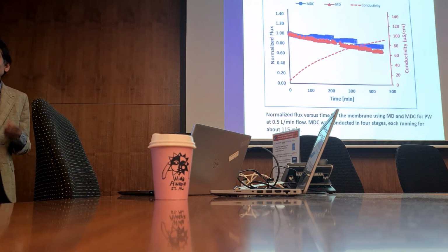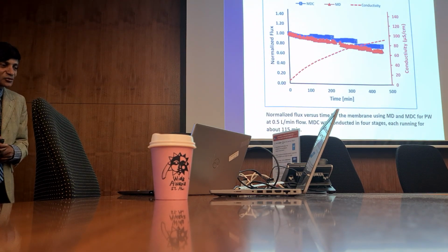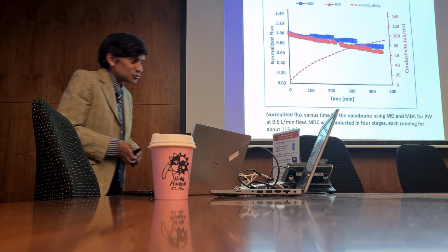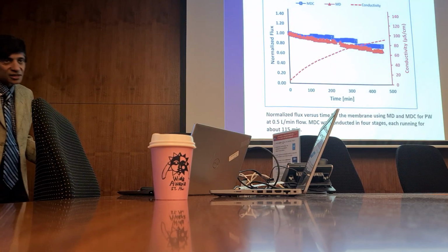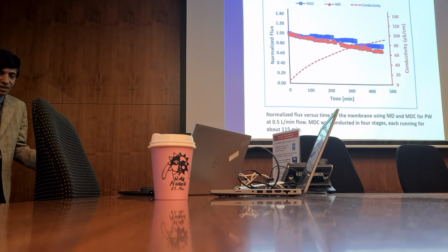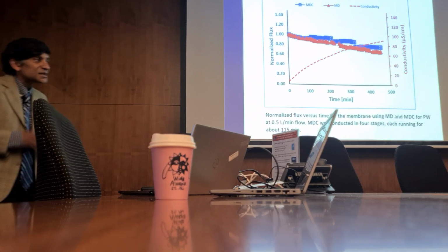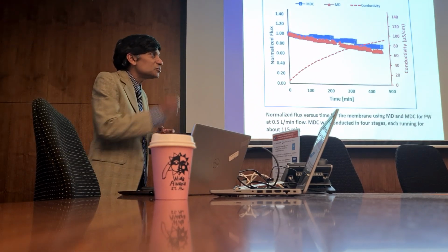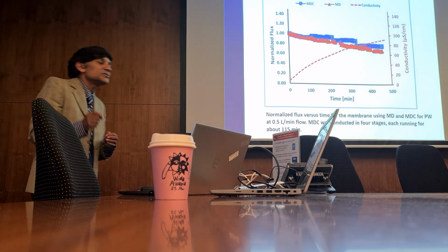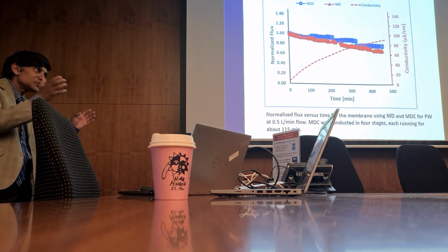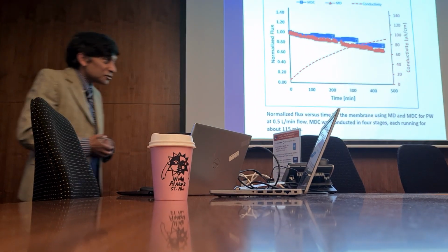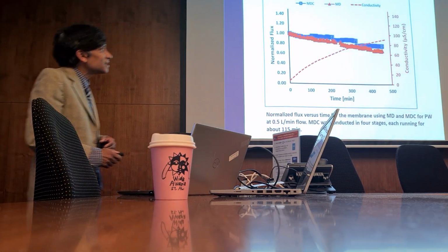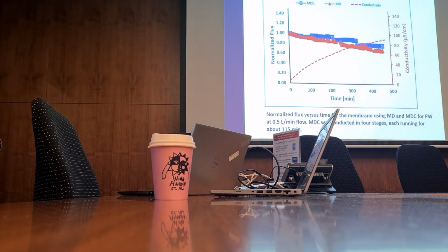So while in the literature there's a lot of work that suggests that membrane distillation and crystallization could be viable, there are a number of problems with it. The first is, of course, it's much more energy intensive, right? A crystallizer takes up much more energy. Secondly, it is really not that easy to run because you don't want any sort of scaling on your MD membrane. You want all the scaling to be in the feed tank and then run this. And you can try to do that, but it turns out to be quite tricky. And actually, in terms of water recovery, we were not able to recover a huge amount more water.